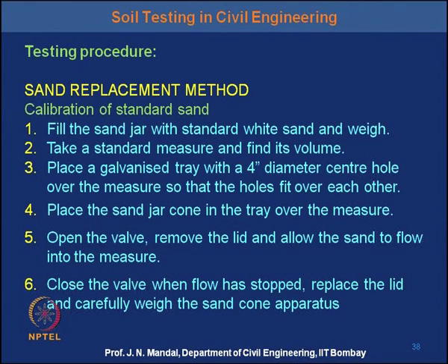Then place a galvanized tray with a 4-inch diameter center hole over the measure so that the holes fit over each other. Place the sand jar cone in the tray over the measure.